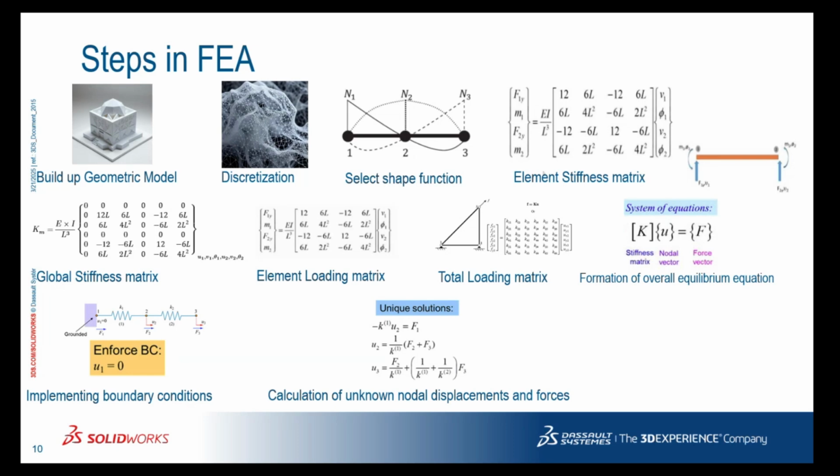Then you formulate the equilibrium equation. In that equilibrium equation, you implement the boundary conditions, and by solving the equilibrium equation, you get the unknown nodal displacements and forces. So this is the typical procedure which goes on beneath the FEA.